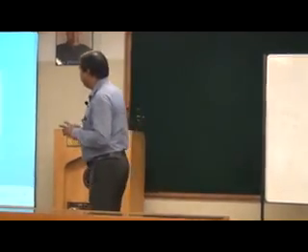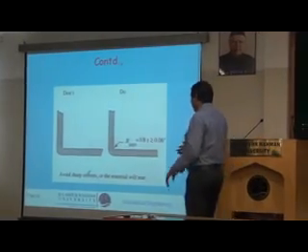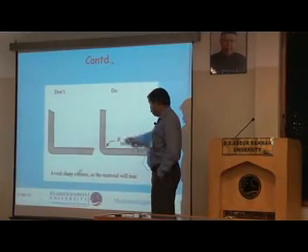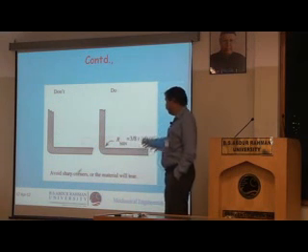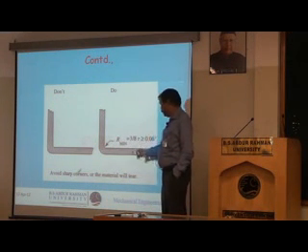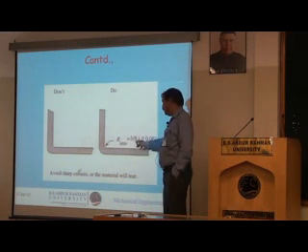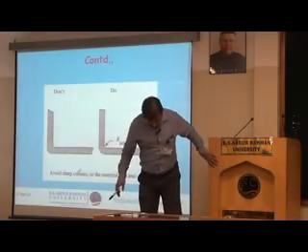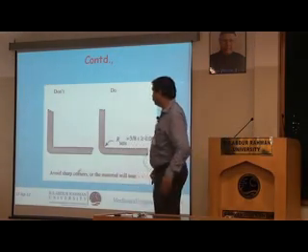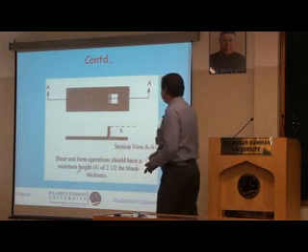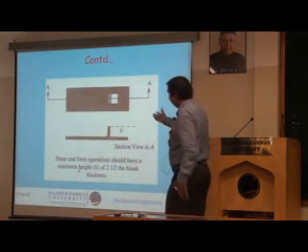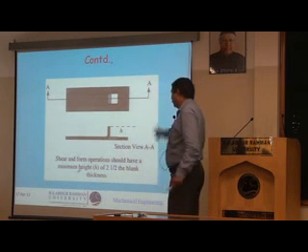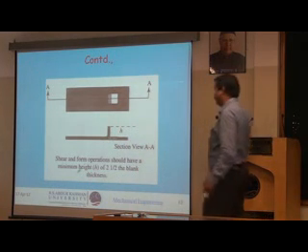Next slide please. Similarly, here you should have a minimum radius, otherwise it cannot be made. The minimum radius must be equal to 0.38 of the thickness. Next slide please. Similarly, when bending takes place, the bending height has a limitation.